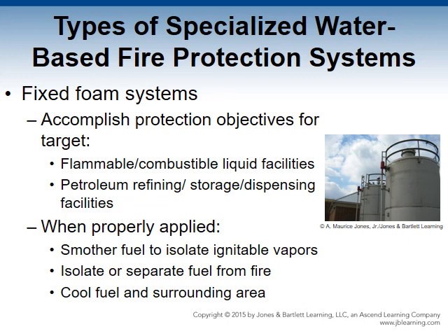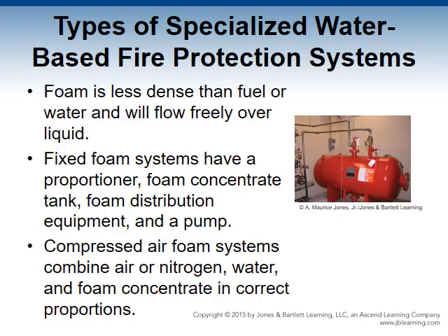When properly applied and proportioned, foam from these systems does the following. It's going to smother the fuel to isolate the ignitable vapors from the air. It's going to isolate or separate the fuel from the fire, and cools the fuel in surrounding areas to prevent further ignition. One manufactured foam product and equipment cannot combine with another unless listed or approved for that purpose. The ingredients must be mixed in the correct proportions in order to do the job effectively.